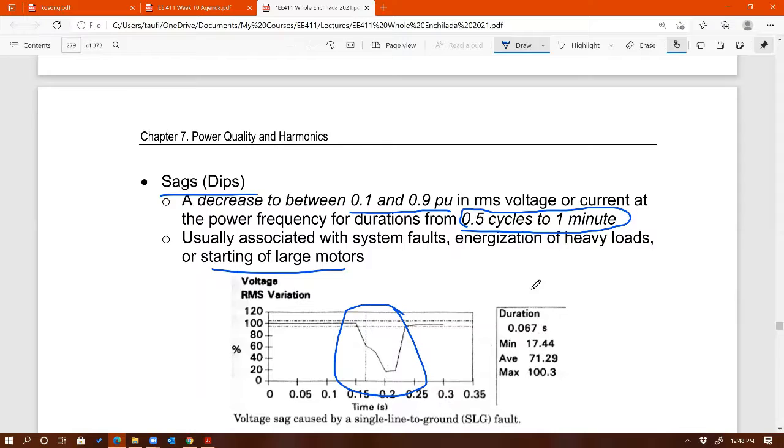So at the beginning, when you turn on the power, you are connecting voltage across this inductor, right? At the very beginning no flux is yet produced, so this inductor acts just like a short, basically. And now you know why. As you know, if you have a short, then you have a big current flowing, right?